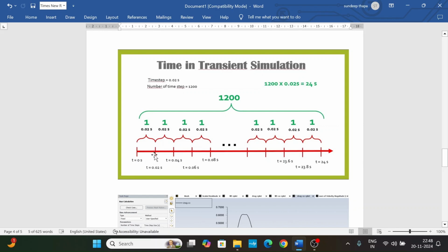Your convergence will be reached faster, and then again for the next iteration. Let's say you have given 30 iterations, 30 calculations would be done for each mathematical model, and you will reach convergence somewhere between 0 and 30. Same for this one, and this one, and so on for 200. So do not increase your iteration value in a large amount. If you want to tweak something, change these two parameters. You can decrease this parameter.